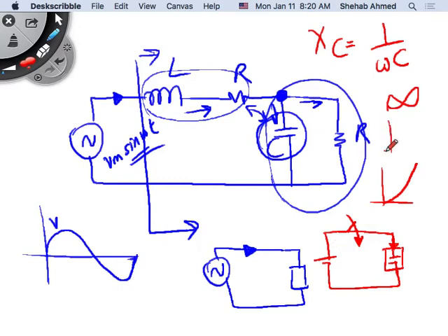So you'll find that the capacitor current changes instantaneously and starts charging the capacitor, right? And then decays exponentially, like Khaled was saying, until the capacitor voltage reaches the source voltage. In that case, there will be no more current flowing, right? So that's in DC circuits with transient switching analysis.